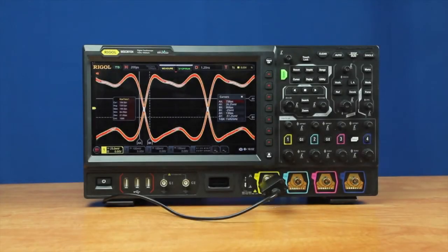Bandwidth is an important specification for any oscilloscope, but it's often hard to visualize how that might impact the measurements you make every day. Many engineers utilize a scope without sufficient bandwidth for the task, but adjust the amplitude on the display to see the signals that are attenuated. This isn't the whole story, especially when conducting signal quality measurements on critical embedded signals. The real-time eye diagram test is the best tool for complete signal quality. Let's look at how bandwidth affects the results of your eye diagram.